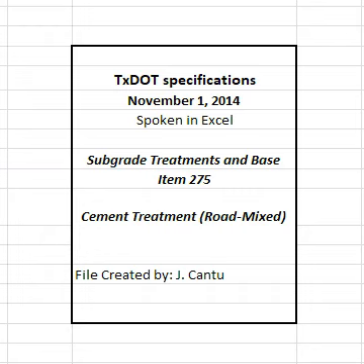After mixing, the engineer may sample the mixture at roadway moisture and test in accordance with Tex-101-E, Part 3, to determine compliance with the gradation requirements in Table 1. When strength requirements are shown on the plans, the engineer may sample the mixture to verify strength in accordance with Tex-120-E and adjust cement content to achieve the target strength for work going forward.